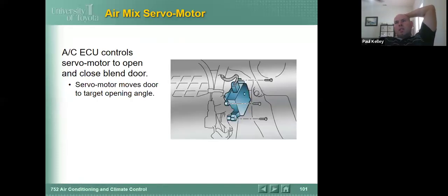Cool. And then this is going to get into what Toyota would call the servo motor. ASE will call it a temperature actuator. Okay, this is an electric motor, but it's a little bit more than that. So we're going to look at the wire diagram because it's a motor, but it's also a sensor, and that's where there's 5 wires. 3 of the wires are a position sensor.